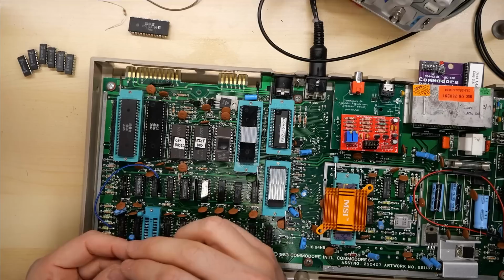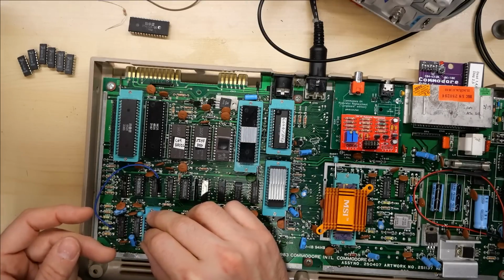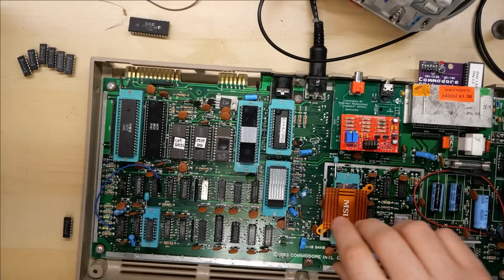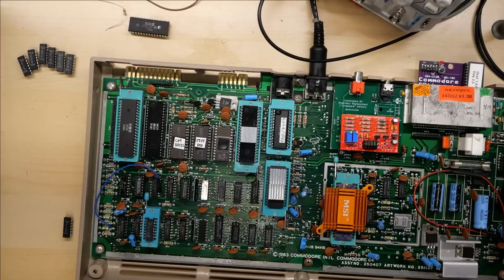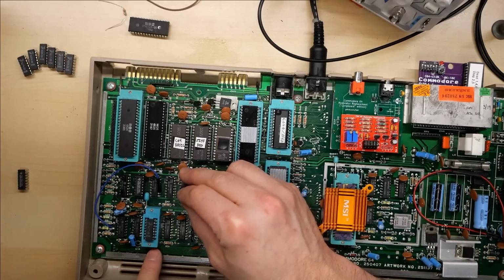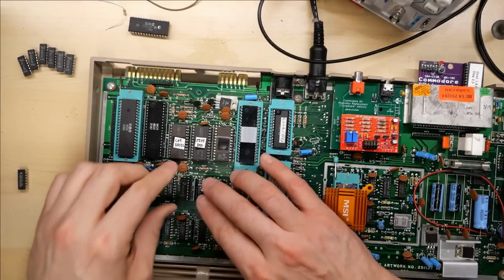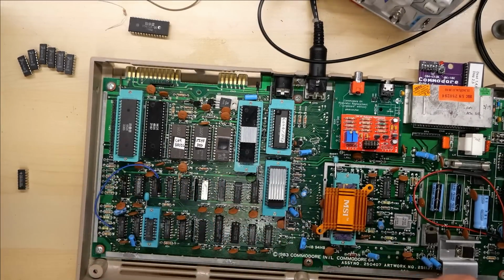Although, what's going to happen if I put 2 of these in? Let's pop with this one in here, and I'm going to switch one of these other good chips out with the other bad chip here, and we'll just see what happens exactly. So one bad RAM chip is in U22, and the other one is going to be going into, what is this, U12. There we go.